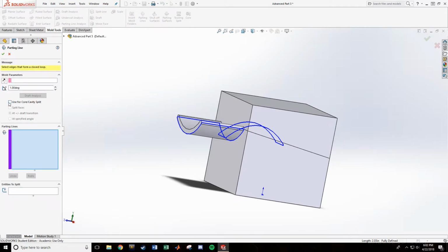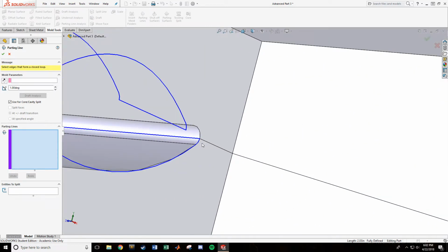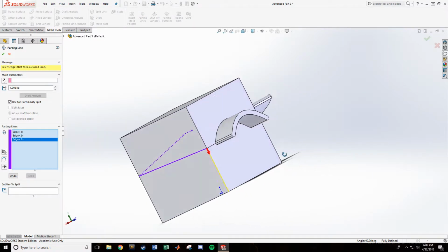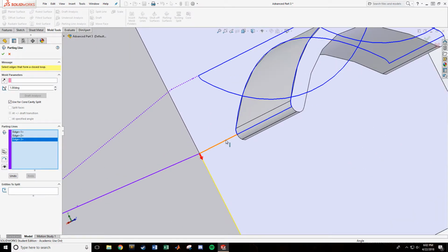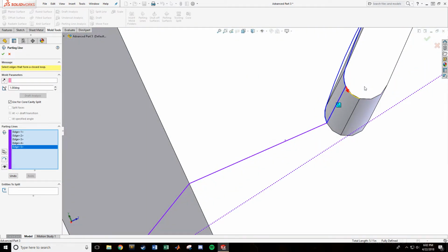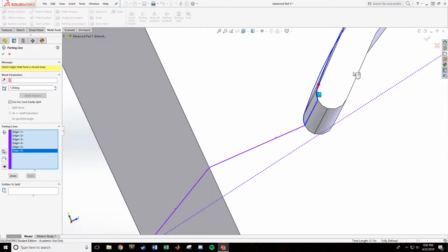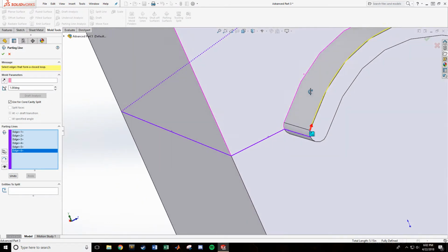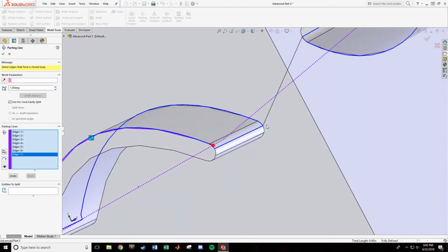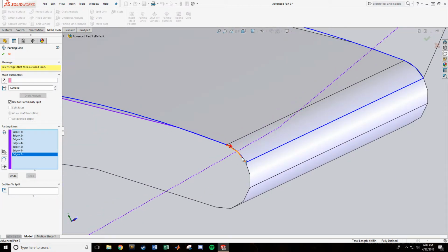Next, we're going to make another set of parting lines. And it's really important that we check use core and cavity split here because this is what we want for our parting surface. And again, as I mentioned before, it's really important that we select all the lines. The thing that I've found the easiest is start at one location that's easy to identify and just go the entire way around without skipping anything. Because right here, you can't see if we've selected these or not, because they're already parting lines and they're already blue. So it's really easy to miss these, and we don't want to do that.